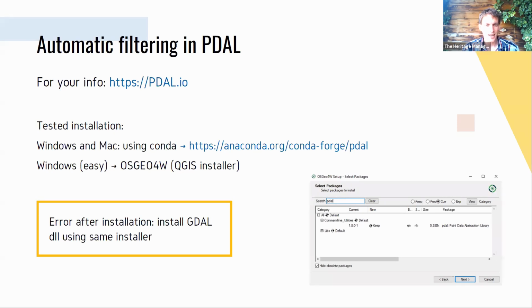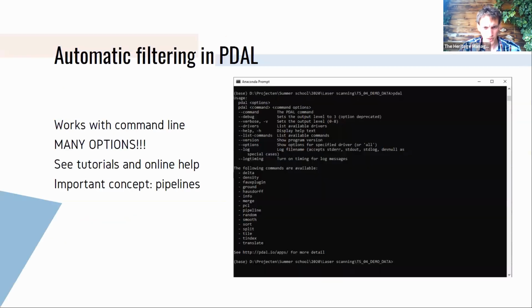At least for my laptop, it was impossible to do that in CloudCompare. So I wrote a script in PDAL, and PDAL allowed me to process these data automatically. It was just a matter of pressing enter, and the day after I had my processed data set and point clouds that I could use for further data processing in QGIS and AutoCAD in that case.